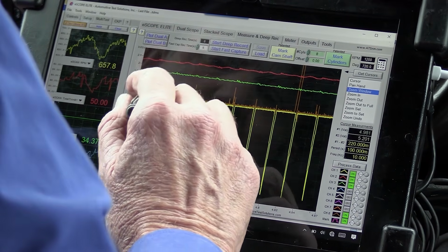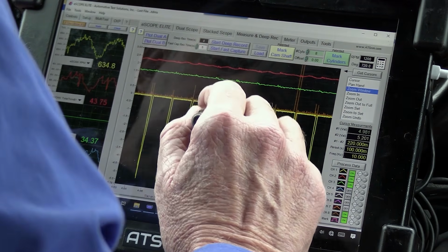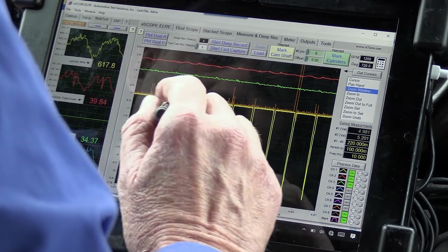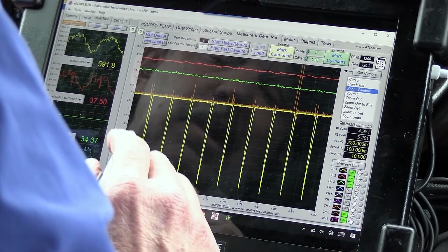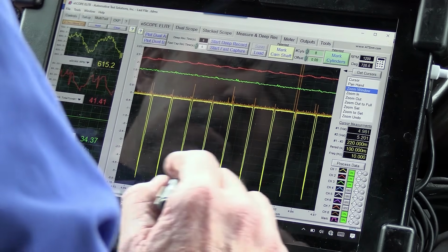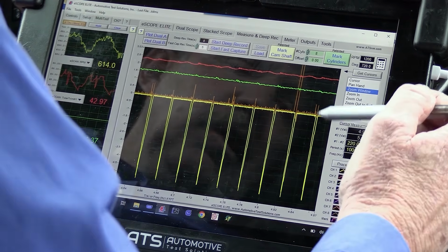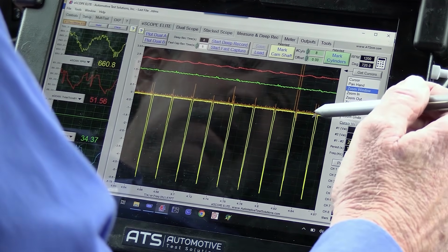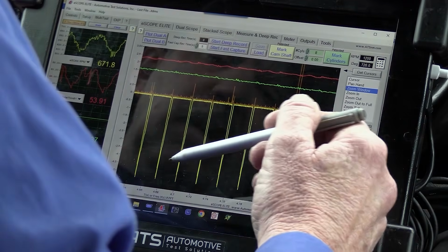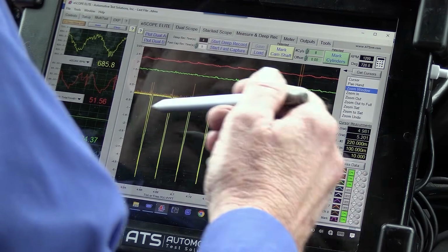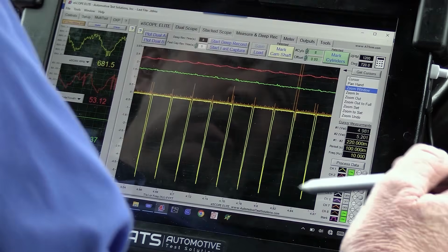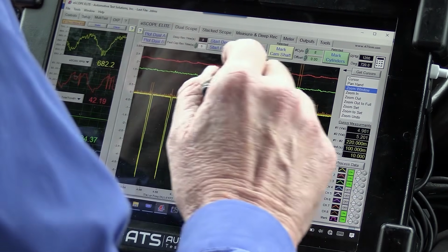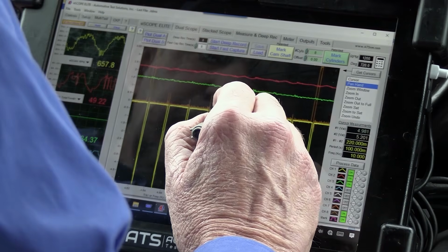Okay, so all of the current flow to both solenoids is equal. We can see that. And that's about 5 amps, and that's what I expect, so that's good. The most important thing is one isn't low and one's high. They're all about the same, and I know they're going down, but the amp clamp was really difficult to get on, and I got it on backwards, and then I didn't invert it in my setup. But it doesn't make any difference. They're all equal. That's the most important thing. They're equal. Now what I want to make sure is, is it failing up here like it was before?